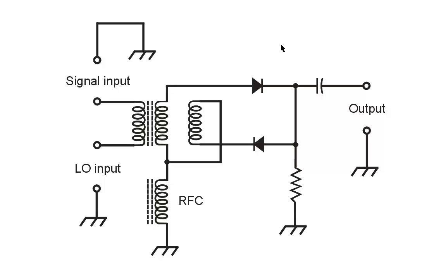Getting back to the subject at hand, what is it that makes this thing work? What is it that makes it possible for us to take a single sideband signal like this and an ordinary unmodulated carrier from an oscillator like that and get audio out there? And the answer is that these 2 diodes in this particular circuit do that. This circuit is called a passive product detector.